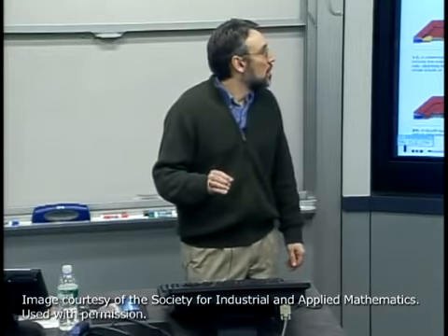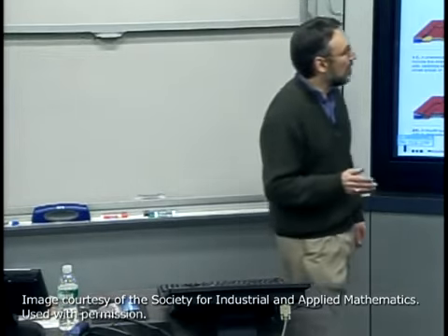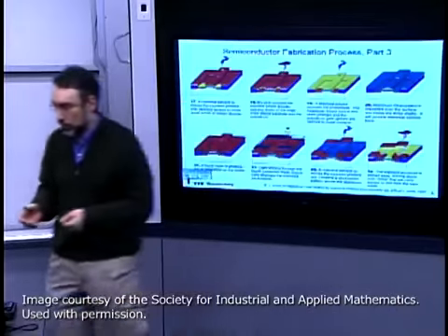Now typically what's done for metal layers is some form of a physical vapor deposition, where one example is a metal evaporator where the wafer will be positioned some distance away from a metal source. The metal source, aluminum or other materials, will be heated up either directly electrically or under sputtering kinds of activity,